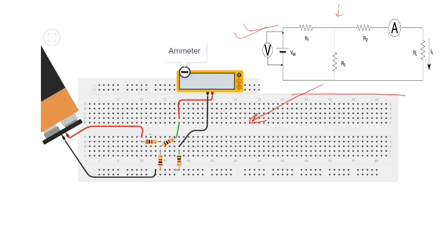So this is your resistance R1. This is R3. This is R2. And this is your resistance RL. Okay. So what I have done here is I have removed one terminal of resistance R2 from here and inserted an ammeter in between so that my ammeter comes in series with the circuit.